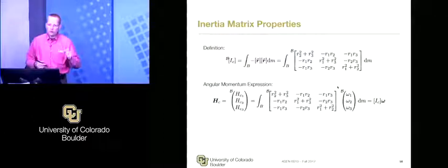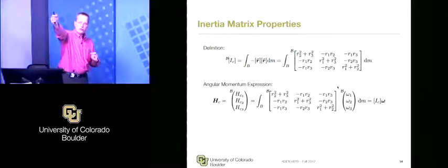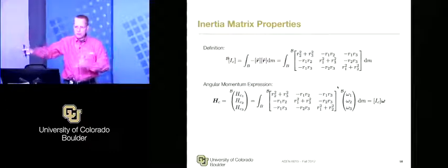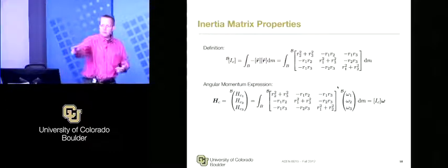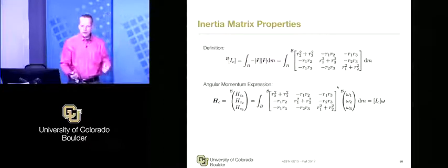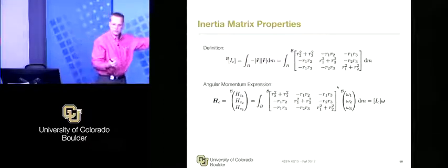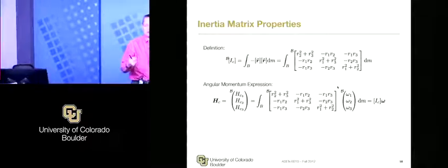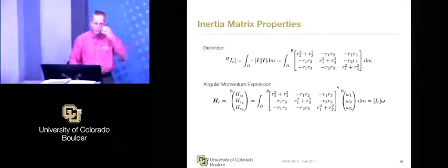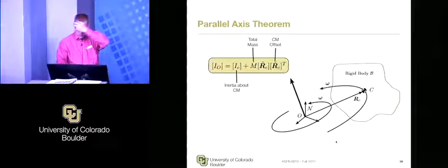Exactly. So as you did, if you have vector components taken relative to B, and you need them relative to C, you have that vector times the CB DCM, which maps it from one frame to another. So the vector is kind of like a 1D tensor. The inertia is a 2D tensor, so instead of using the DCM once, we have to use it twice. Pre and post multiply. So that's just some highlights. Let's go through the slides. You're remembering some of this stuff.